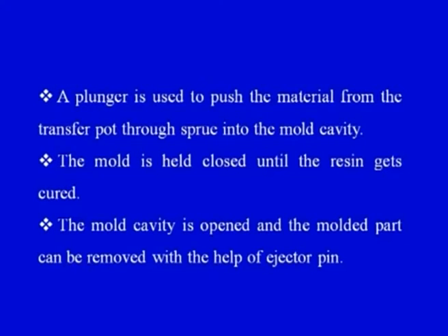Now the curing process we have also seen in lecture number 1, where we saw that thermosets cure irreversibly and thermoplastics cure reversibly. So in that differentiation of what the curing process is, I emphasized that curing can be achieved under heat, or it can be achieved by the reaction of a particular polymer with a particular hardener.